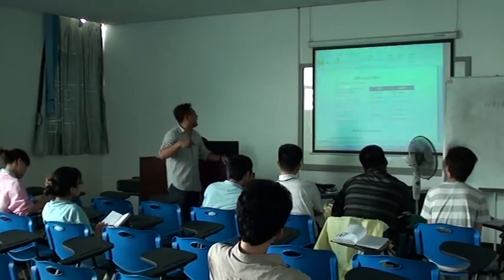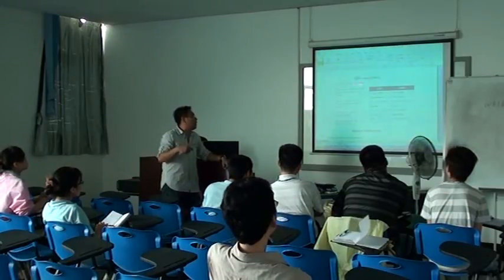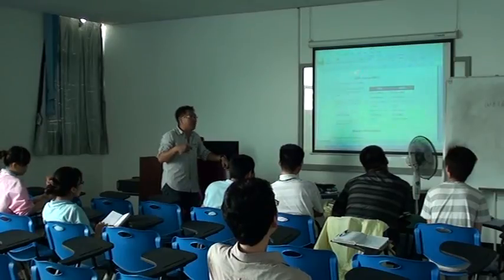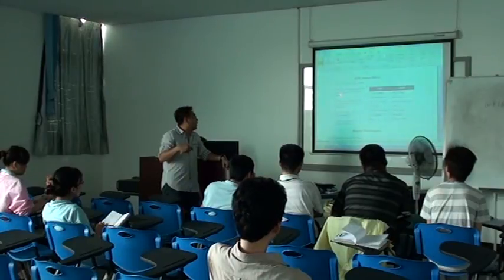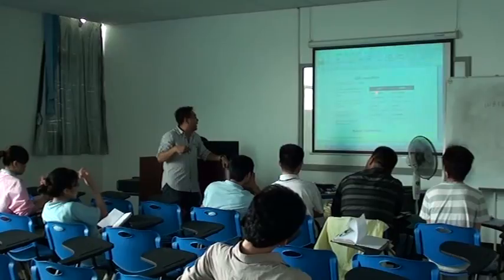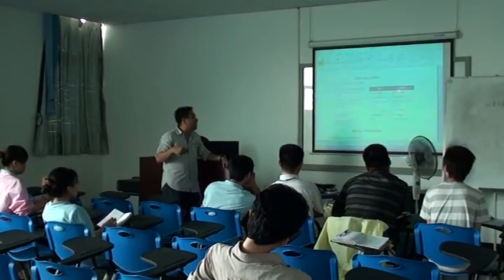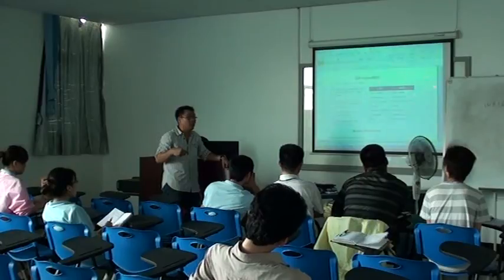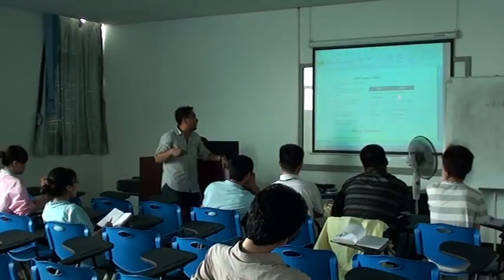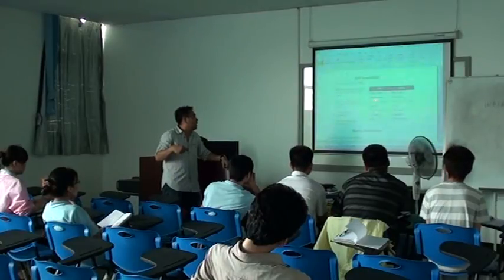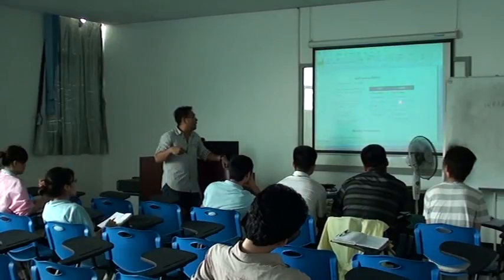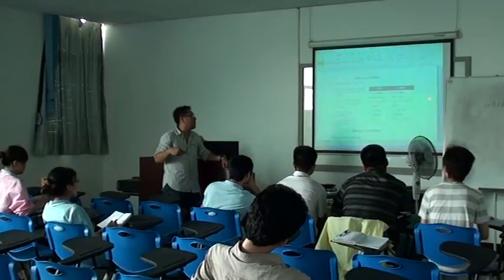So, as you know, DDR1 is about 15 years ago. It's very similar to DDR2, but the core is different, right? DDR1 is 184 pin, but DDR2 is 240 pin, and DDR3 is 240 pin. So that's the difference. The same 64-bit data bus. But with technology today, it goes up to 200, 400, 500, 600, 800, up to 1066, or up to 1600.